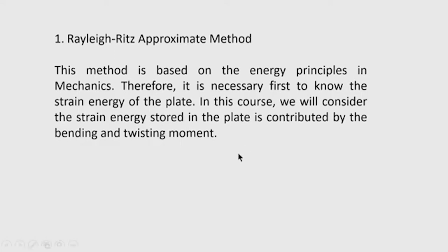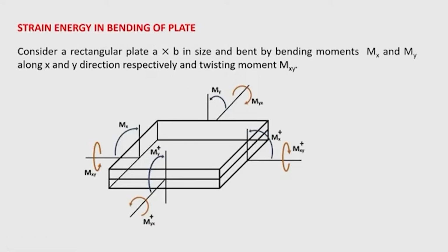However, Rayleigh's method does not restrict that one has to use only the strain energy expression for bending moment and twisting moment. One can include the shearing deformation as well as in-plane forces in the strain energy expressions. Okay. Now, let us see the strain energy expression for the bending of a plate.